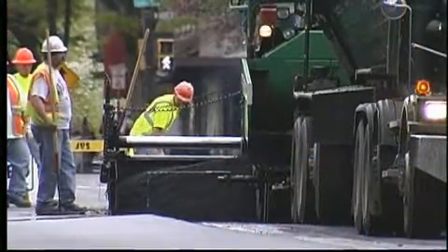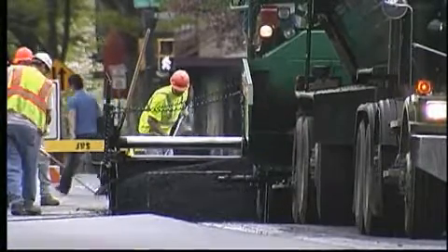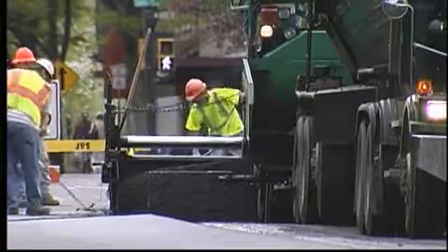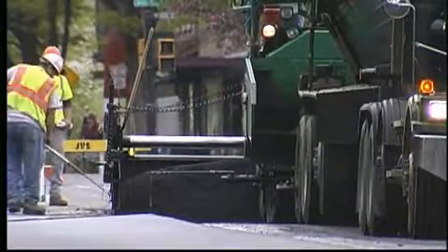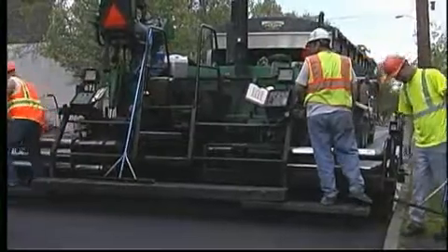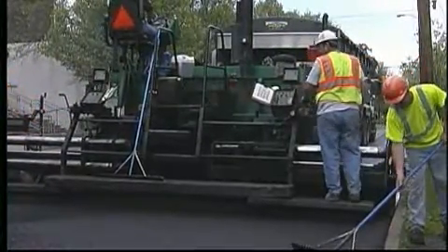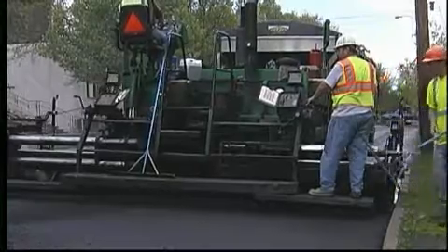One of the reasons we calibrate falling weight deflectometers is to improve the quality of the actual data that we use in pavement analysis. Systematic errors in FWD data will affect the design. Using an overlay design as an example, underpredicted deflections could lead to a thinner overlay that may not last as long as planned. Overpredicted deflections may result in excess costs due to extra material being placed. These monies could have been applied to other projects.